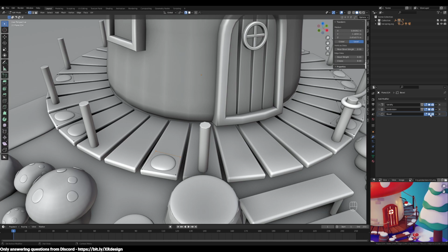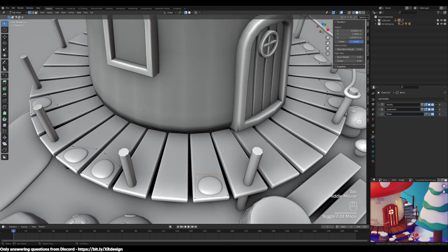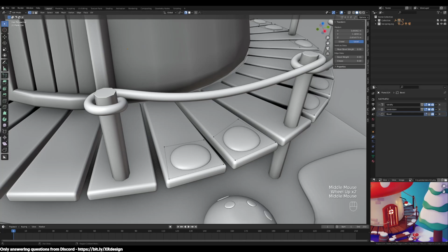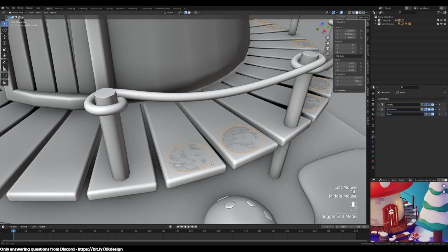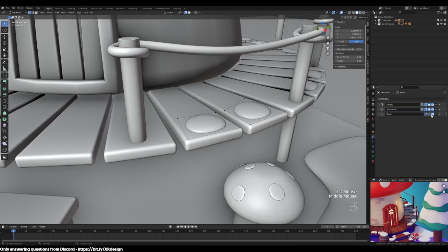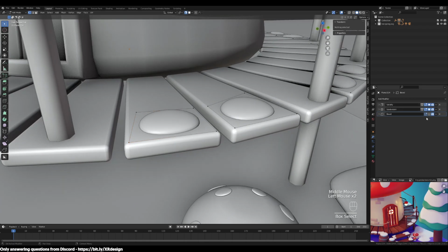So if I had to remove the bevel to show you, without the bevel, it's trying to curve from 4 points and creating more geometry so that it will look a bit more round, and then Solidify will add more depth to it. Bevel, you're actually beveling these 4 edges. So when I turn this on,